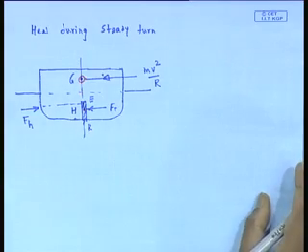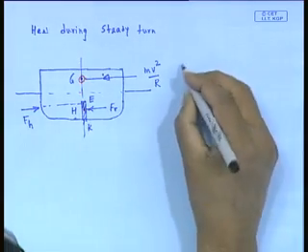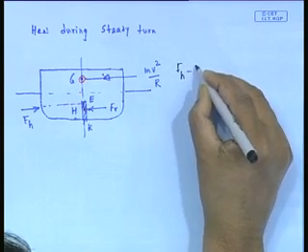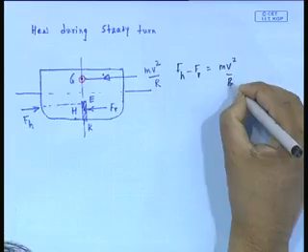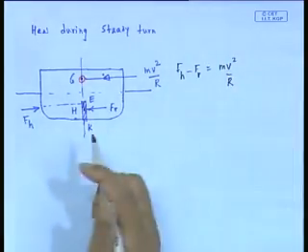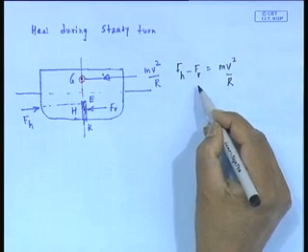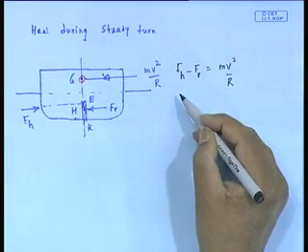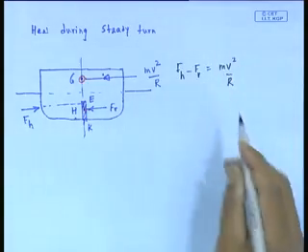And this is my point, keel here. So what we have here is simply FH minus FR equal to mv square by R. That net force has to balance. Total Y force here is essentially 0. It comes from the equation also, because after all FR will be Y delta delta, and FH is going to be YVV plus YRR. Essentially it becomes that, but I am just looking at it this way.